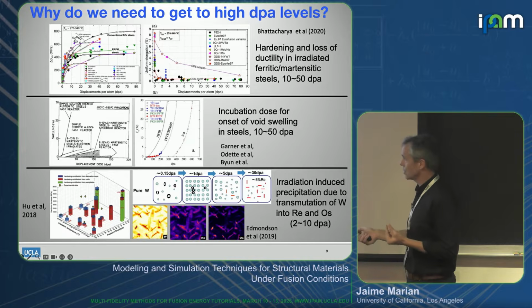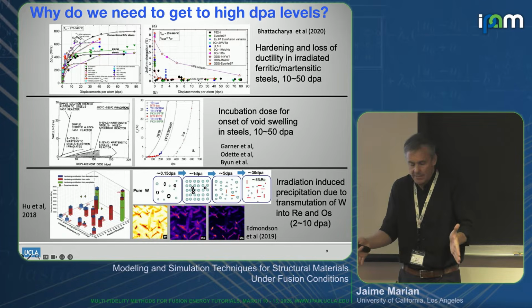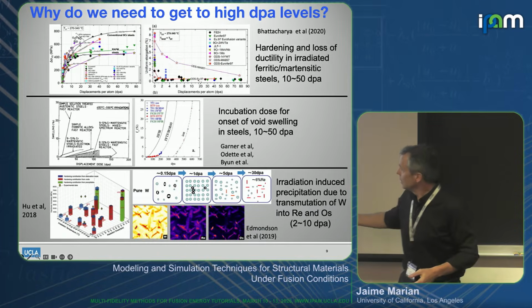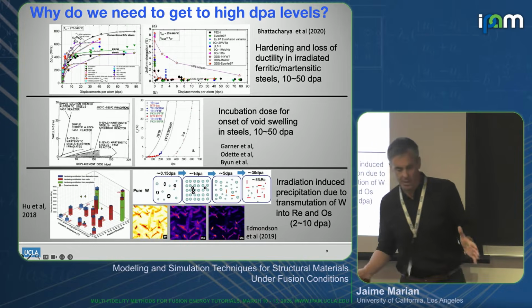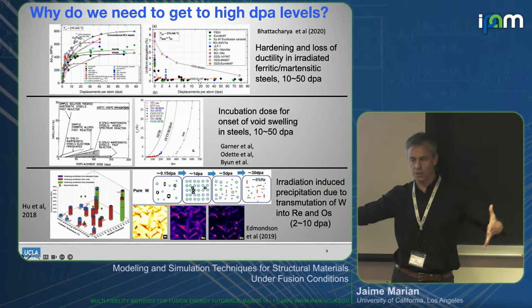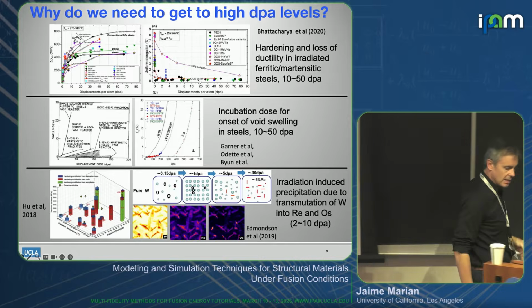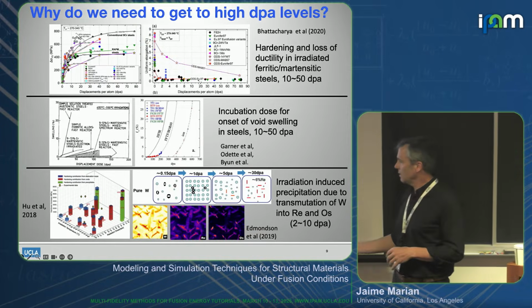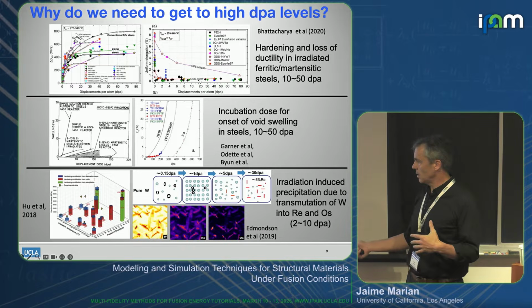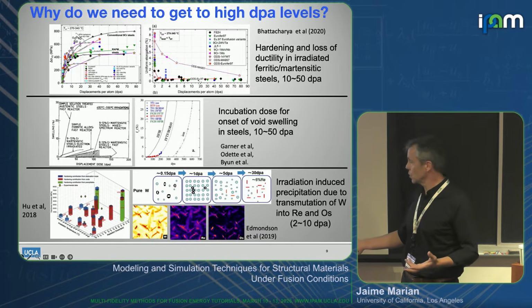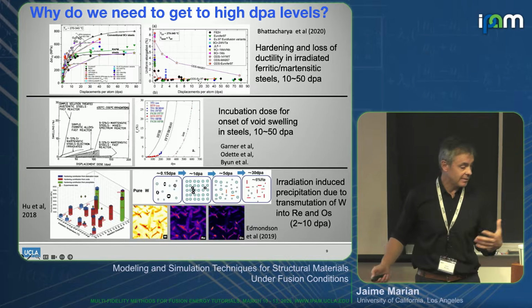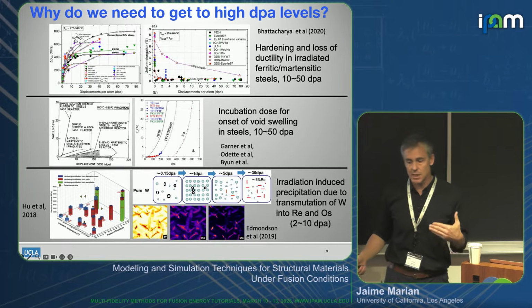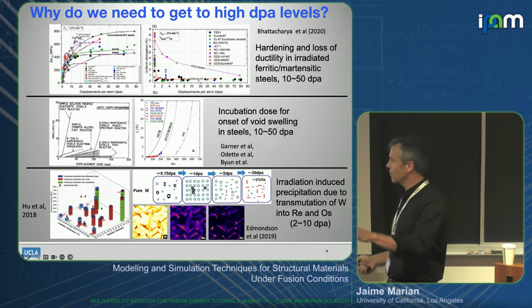really fine tolerances, when you're doing these designs, you can't have a material there that just swells by 15%, 20%, something like that, right? You can think of a large structure just increasing its size. So huge issues. The microstructure can change completely from going from equilibrium thermodynamics to non-equilibrium thermodynamics. Effectively, irradiation, what it does is it drives the system really far from equilibrium.